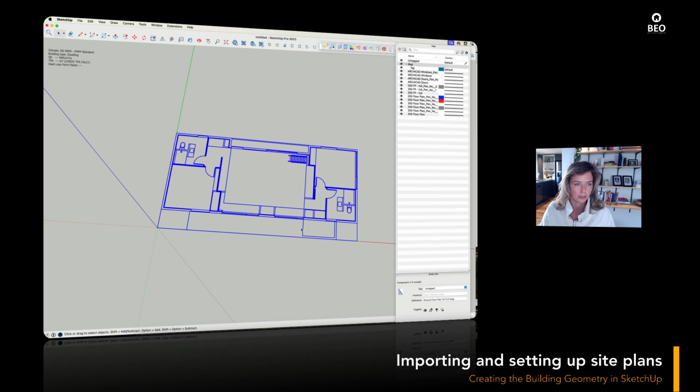So in order to do that, I highlight the drawing file and it shows me the actual name of the file. Particularly in passive house projects where you need to track and trace everything back to architectural drawings, it's handy to refer to the same drawings. So I highlight this, I copy it, and then I'll rename this tag exactly that name.